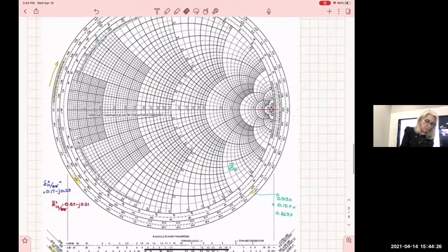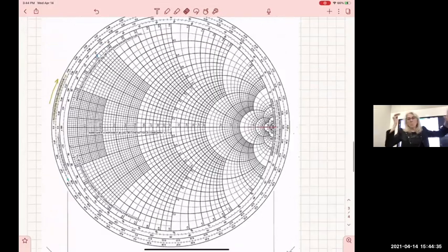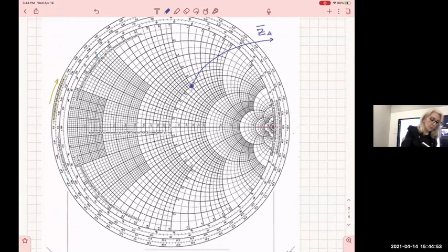All right. If I have an impedance, and then from that impedance, I find on the transmission line the circle for the transmission line. So let's assume I get one impedance just randomly. Let's assume that I get this impedance. That impedance here is Z, and I call it ZA. This is ZA, and it's 1 plus J1.